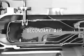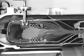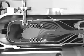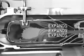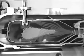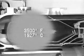Two important events occur here. The air cools the hot combustion gases before entering the turbine section, and the air is heated and rapidly expands. Without this cooling air, the combustor would be one big fireball at about 3,500 degrees Fahrenheit, and metals in the turbine section cannot tolerate such temperatures for long.